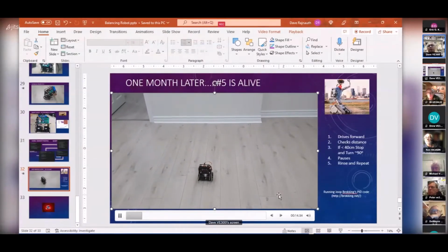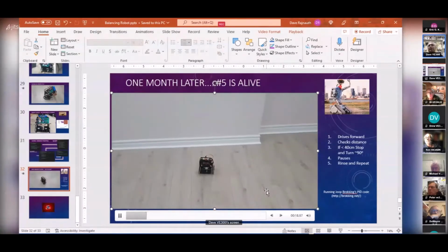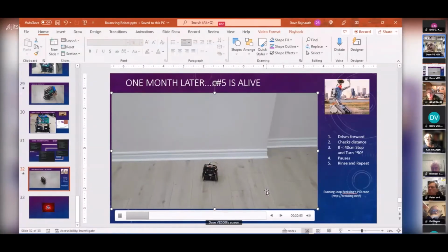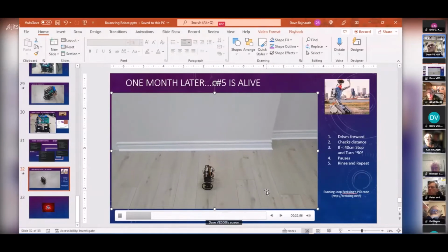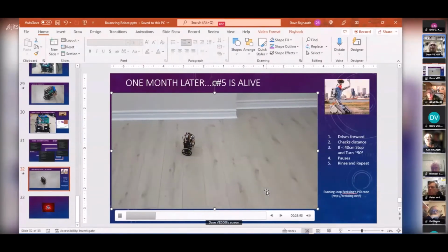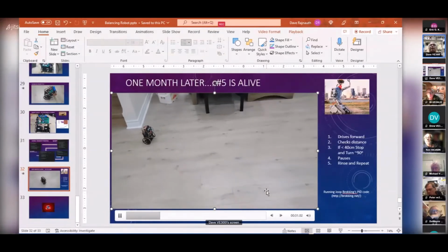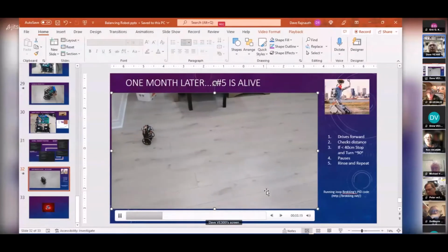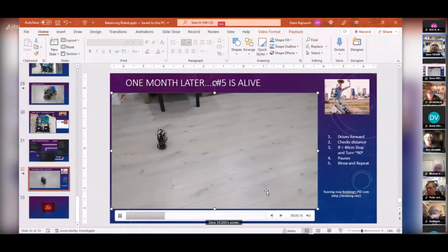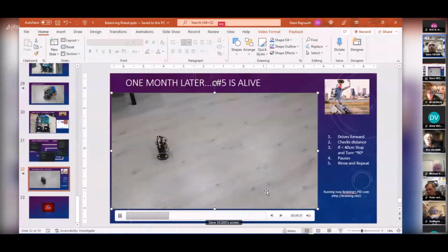Now, the reason why it's speeding up and slowing down is because the speed control is like a PID controller. There it's turning 90 degrees, or it's trying to turn 90 degrees. It speeds up and slows down because the speed controller is kind of like a PID, but I only have a proportional term. If I wanted to do this right, I'd do a proper PID to control the speed.